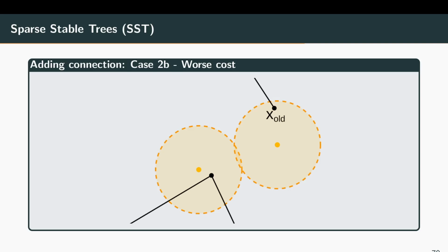I agree, it's actually quite tricky. In these figures, it's still the geometric case of SST, but in the kinodynamic case, you might lose some solutions that are needed. That highly depends on your dynamics. If you have dynamics that highly depend on the exact position, like a narrow passage problem where you really need to be exactly in front of the narrow passage with straight wheels, then that can be an issue. I agree.